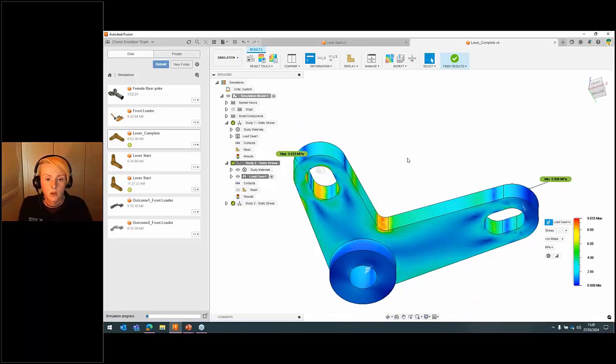So from here, again, we do have that high stress, so we can go back in with a probe. And I think it was 8 point something the last time, so it's up at 9.5. And again, you just need to be careful with the mesh convergence whenever you're working with static analysis, where if you increase the size of the mesh too much or decrease the size of the mesh too much, you end up with singularities.